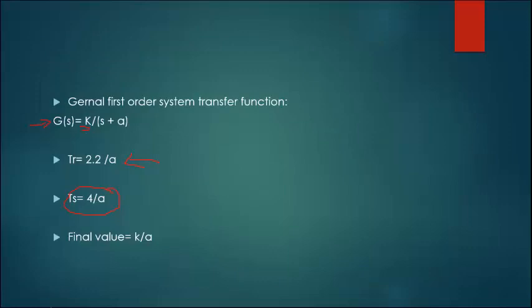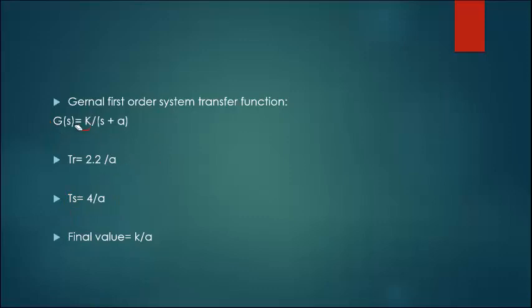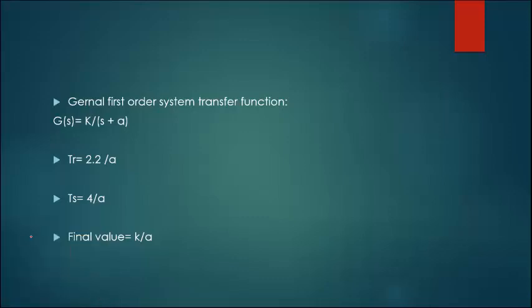So that is typically how you do a system identification for a first order system, but it is not going to be like that in practical systems, because most systems are two or three orders higher. Most practical systems are second order, third order, or fourth order systems, and so on. And even high order systems can be approximated to a second order system.